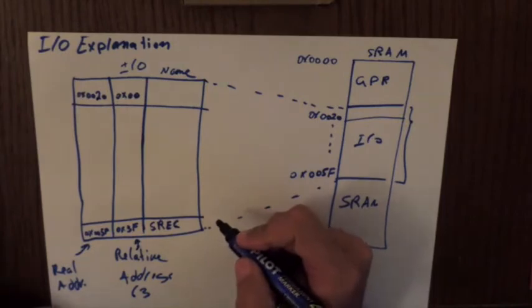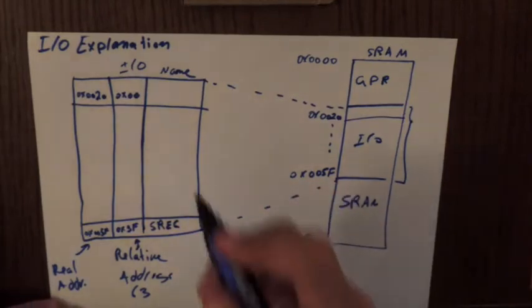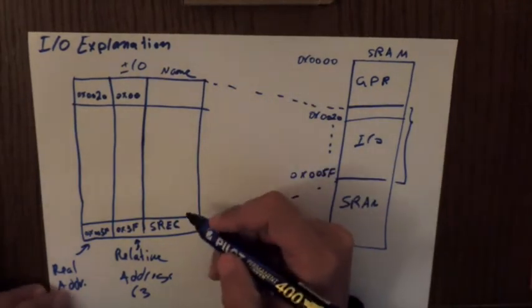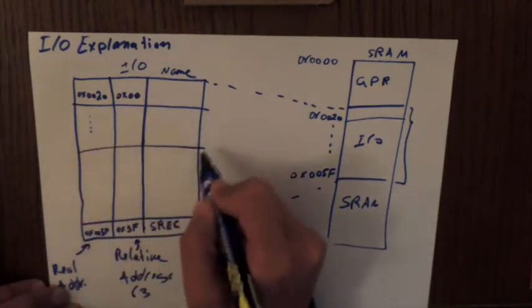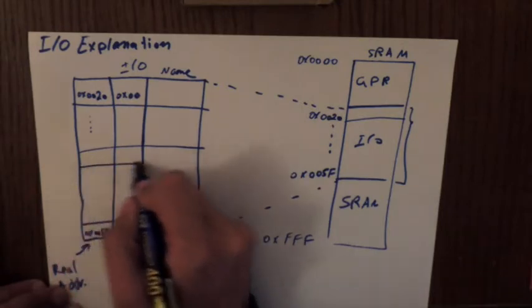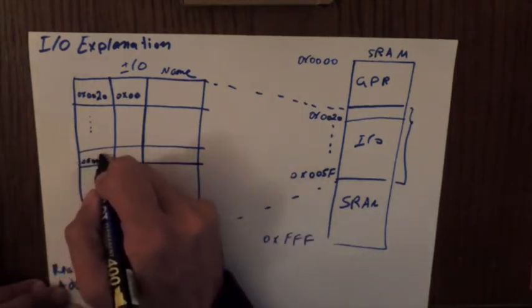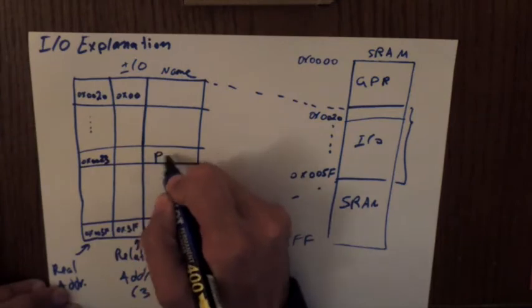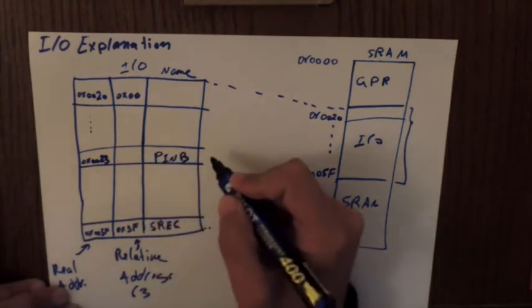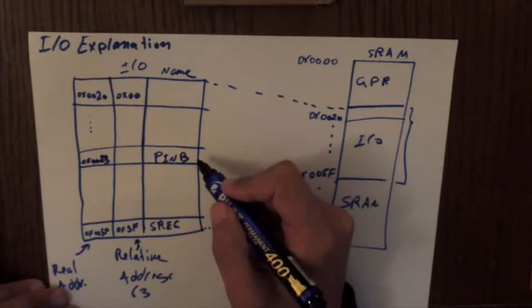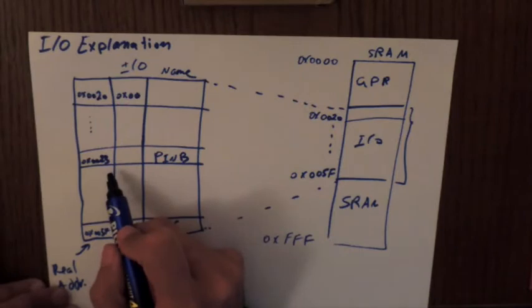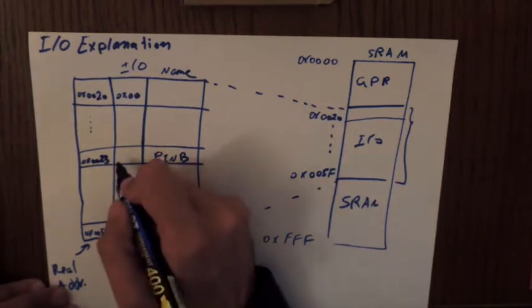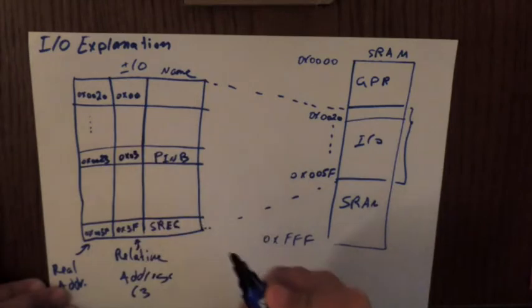has all the carry flag and zero flags and all other ALU related flags. So this is a special type of registers. Again, we saw another register at 0x0023, which is pin B, which has the input port of the microcontroller. Now, to do the transformation, we simply subtract 20 hex and we end up with 0x03.